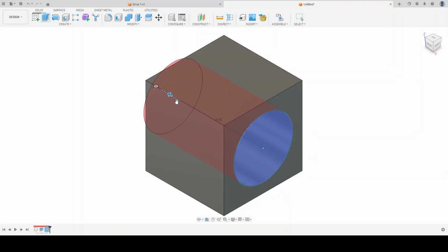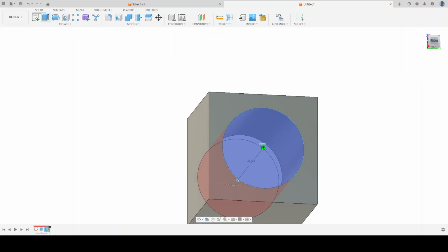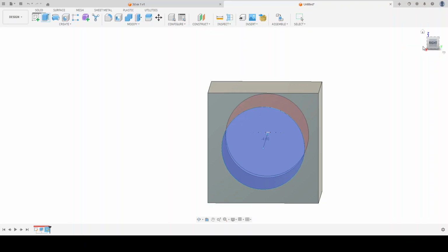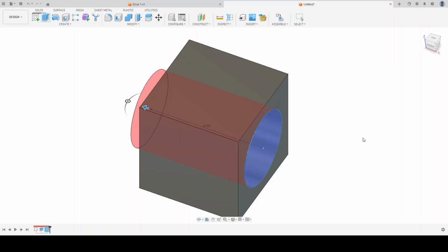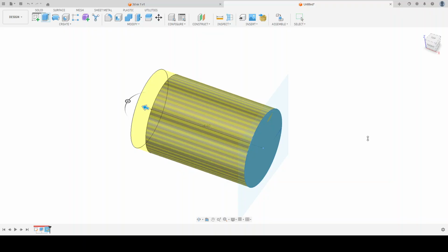If I extrude going inwards, by default, it'll change into what is called a cut operation. You'll notice that the inside gives you a kind of 3D X-ray view, but it's all in red. The red indicates what is going to be cut out. And if you look at it from the front angle, it shows you what it will look like. The third operation, known as intersect, is basically anything that's in this red area where both bodies or both shapes intersect is going to stay. Anything outside of it will get removed, and it'll be indicated by the color yellow.